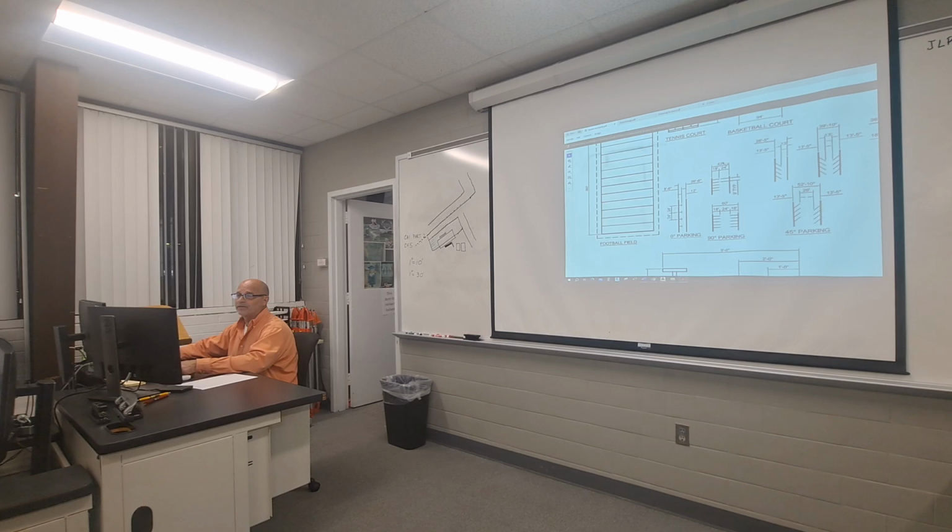The 18 feet and the 42 feet also carry over. Right down here below it in the 90-degree parking area, this is if you've got parking spaces on both sides of the drive. 18-foot parking spaces on each side, 24-foot behind them to pull in and pull out, still 9-foot wide spaces.